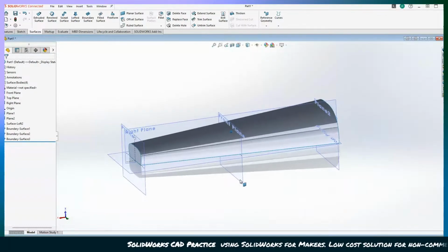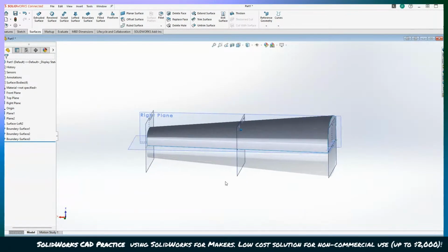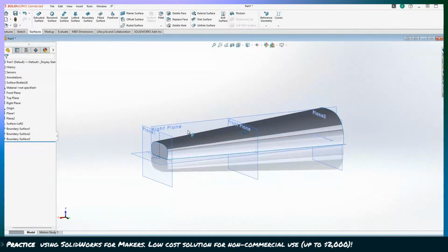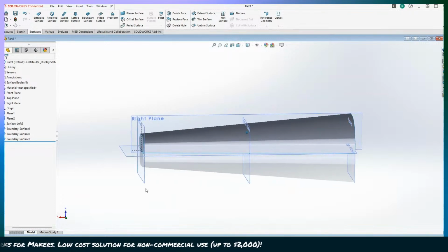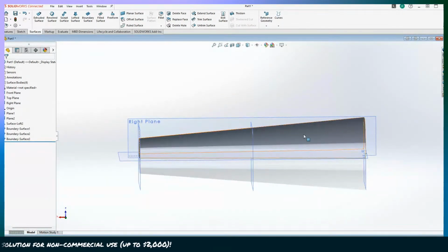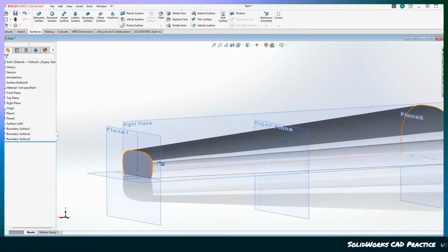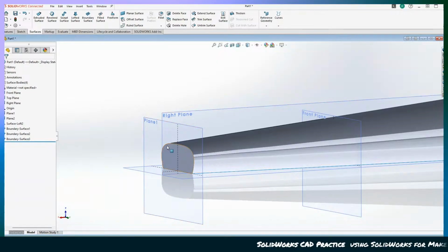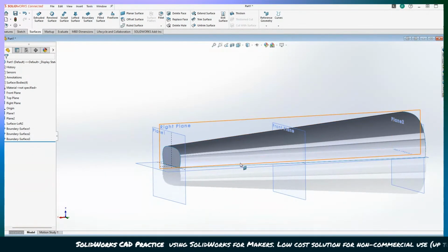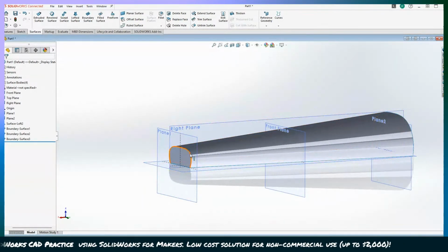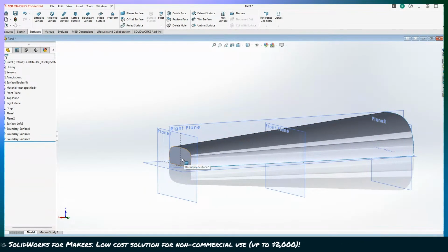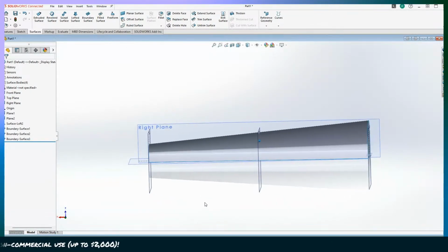So for the handle scale on the fixed blade, or even the axe, I can just create a series of sketches and then create the profiles that I want at each point, and then create that. Then we can do more filleting or whatever we need to make it the shape that I want it to be.